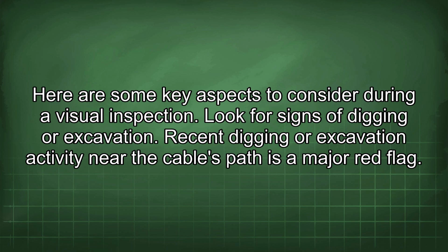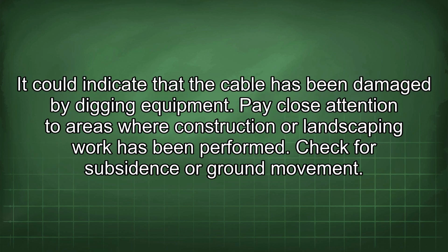Look for signs of digging or excavation. Recent digging or excavation activity near the cable's path is a major red flag. It could indicate that the cable has been damaged by digging equipment. Pay close attention to areas where construction or landscaping work has been performed.